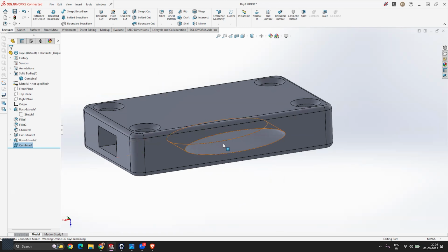So the same extrude cut operation we have performed in two different ways. Either you use the extrude cut operation, or you use the combine tool to subtract the body from the main body, right? Both operations will give you the same result, but we can say these are two different approaches to get the same shape. So which one do you prefer, option A or option B? Which one do you think is easier? Extrude cut, yes, definitely. Extrude cut is simpler, but we should learn the combine tool also. That's why I have given you the demo.